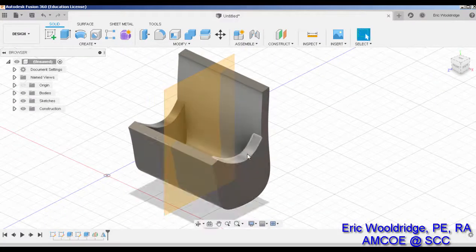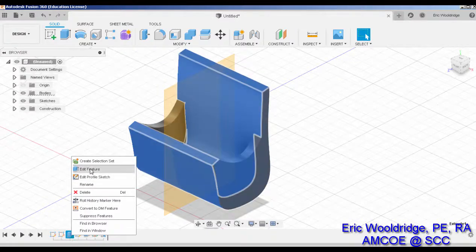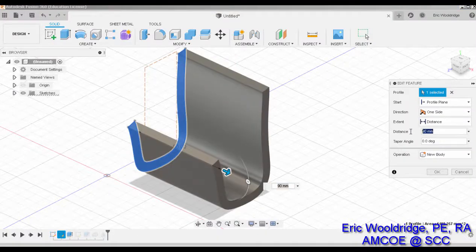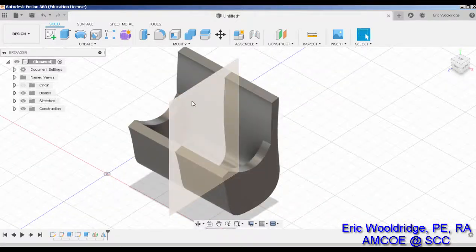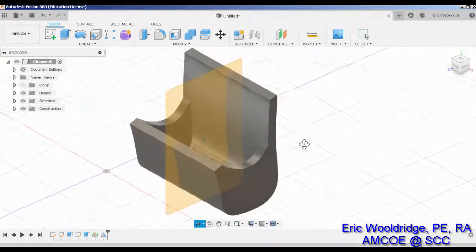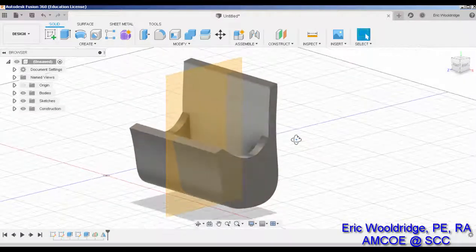And I do realize that I've lost essentially 16 units because of that. As a result, what I'll probably do is extrude this a little bit further. I'll just take it on up to 100. That'd be fine. The reason I set up the midplane and did all that is because it makes it super easy to just have to fix one side versus the other. And there we go. All right, so that's what we have so far. Go ahead and pause the video and catch up to there.